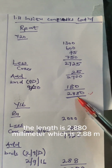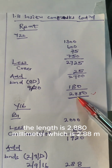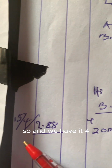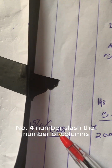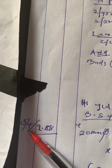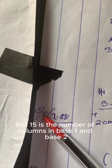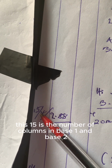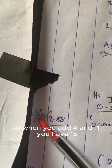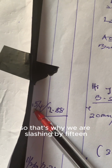Y20, the length is 2,880 millimeter, which is 2.88 meter. And we have it 4 number, slash the number of columns. This 15 is the number of columns in base 1 and base 2. Base 1 is 11 and base 2 is 4. So when you add 4 and 11, you have 15. So that's why we are slashing by 15.